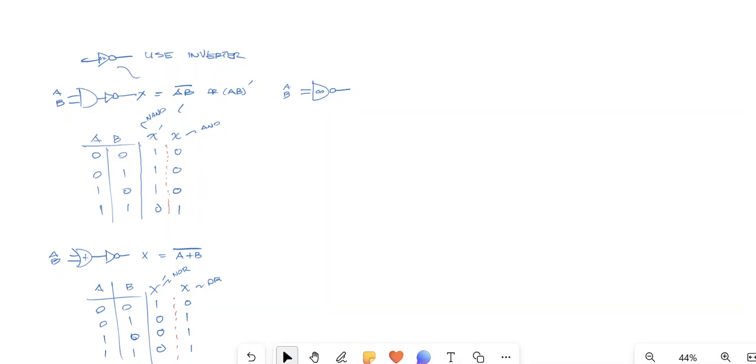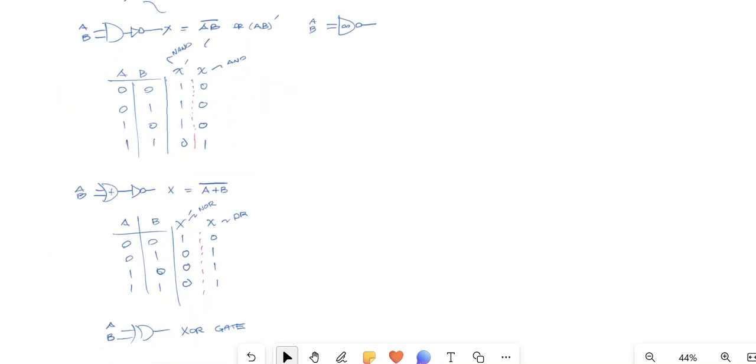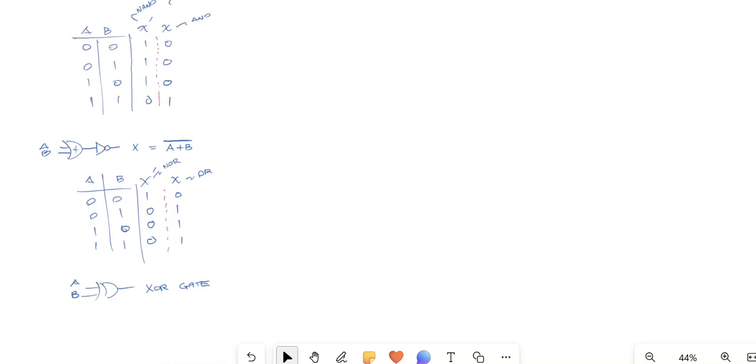So what is the output for a NAND gate? Anytime there's a 0, it'll produce a 1, or on. Now you look right alongside that, that's the representation of an AND gate. So you can see that these are inverted. AND gate: 0, 0, 0, 1. It's the same for the OR gate. This will turn into a NOR gate.